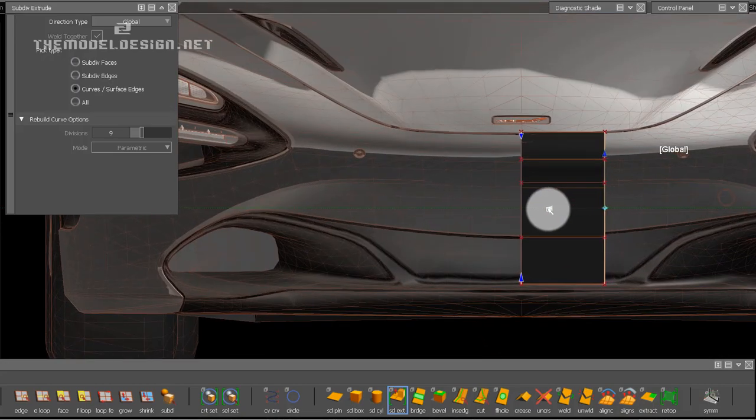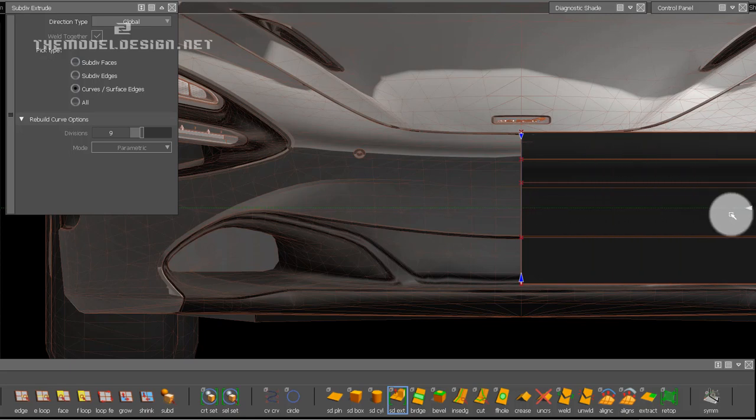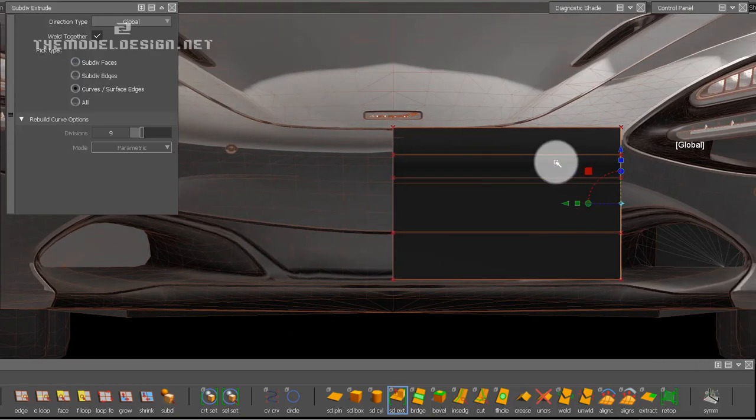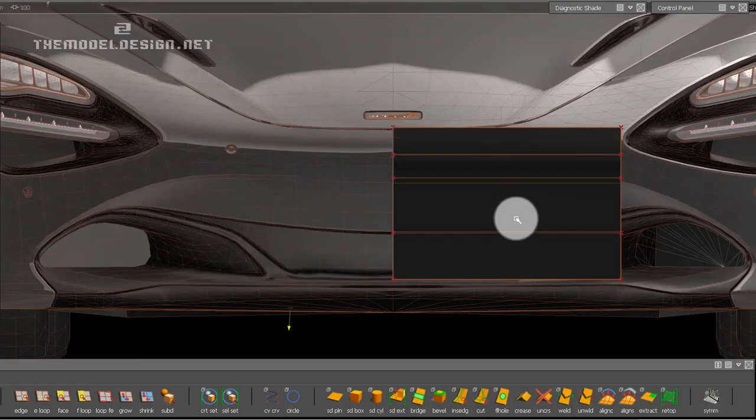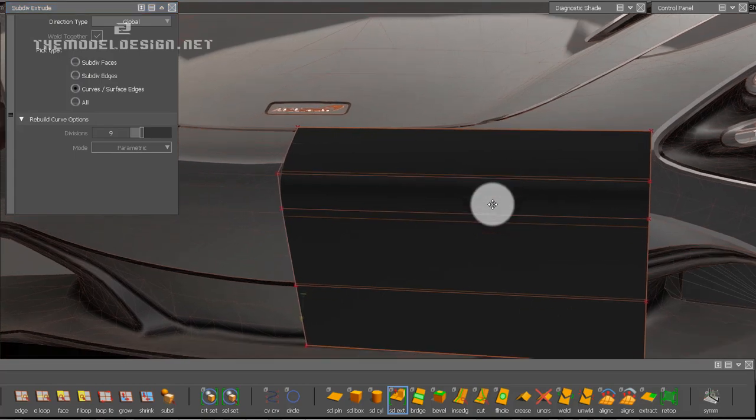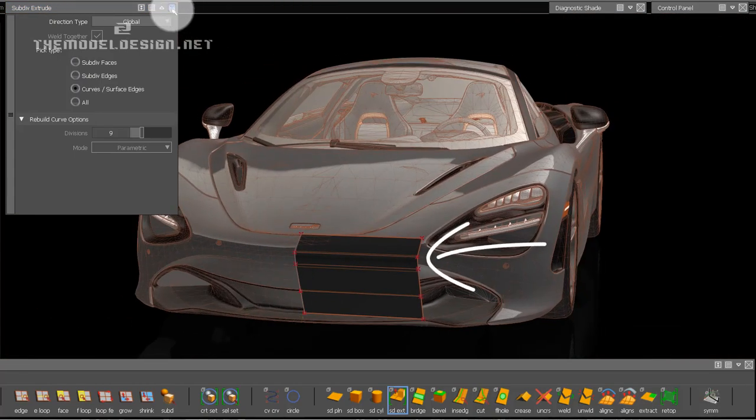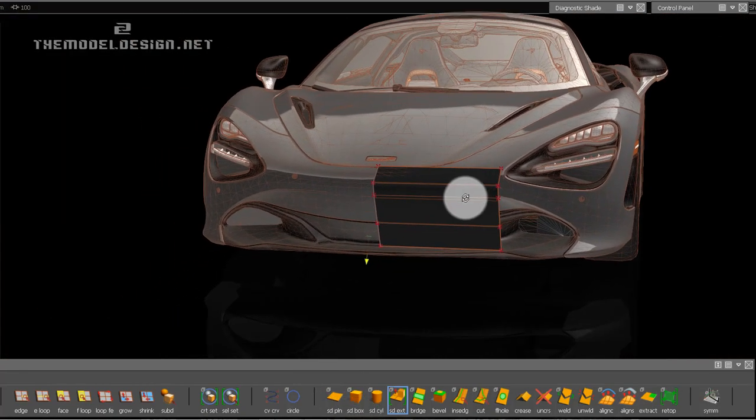I want this patch to be tangent when I take this patch and mirror it to the other side. I want the center area to be tangent. Otherwise, if I move this whole thing in the X direction, I will be left with a kink in the middle.